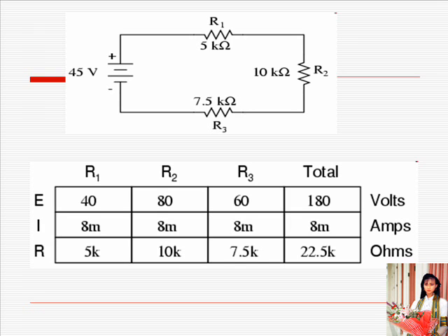Let's analyze a simple series circuit, determining the voltage drops across individual resistors. From the given values of individual resistances, we can determine a total circuit resistance, knowing that resistances add in series. From here, we can use Ohm's law, I = V/R, to determine the total current, which we know will be the same as each resistor current.